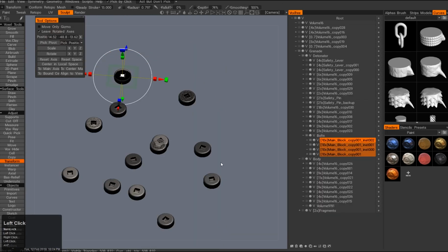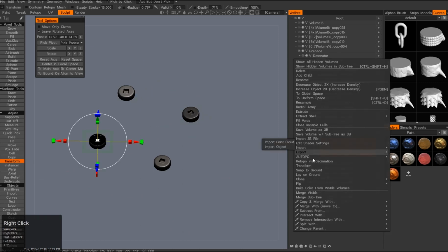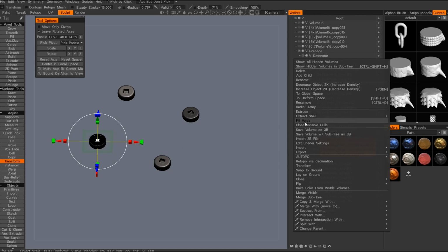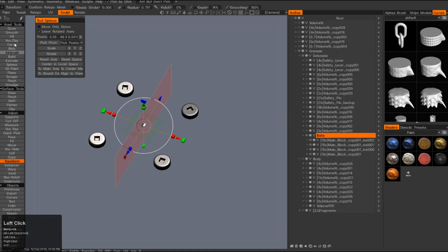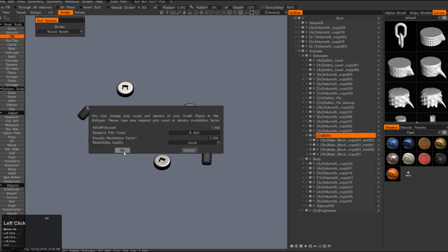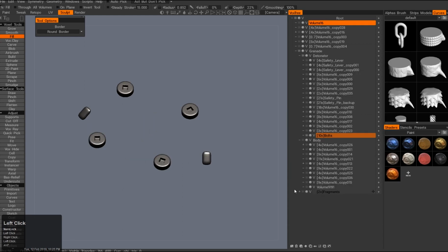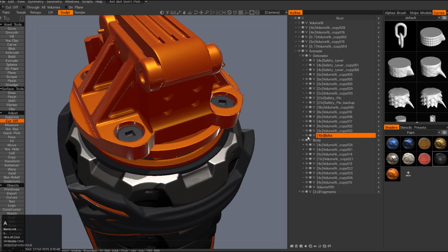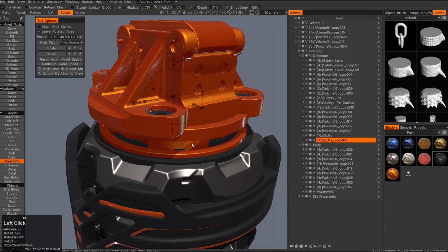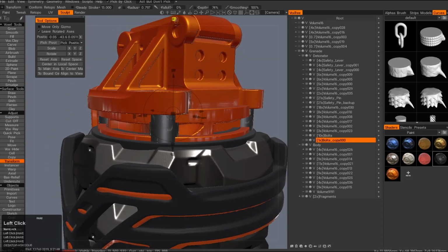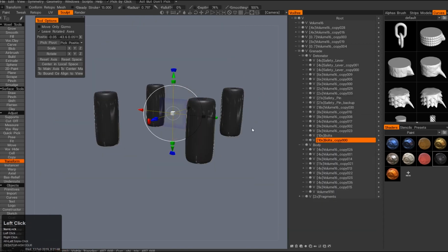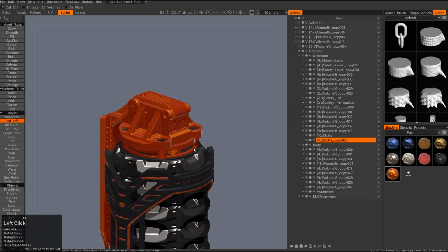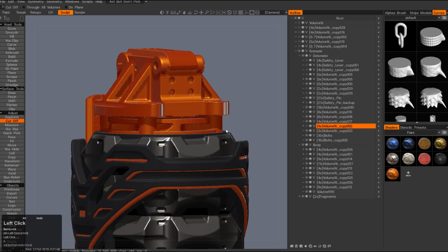Okay, here I was fighting with an issue. I was trying to combine 4 instances together, but if I combine them, then each instance gets extra 3 bolts. And the problem is that an instance in operation is not something that's easy to find. You have to go to the instance tool on the left and use it to uninstance stuff. You can't go into any kind of menu like geometry or symmetry or windows at the top, or right click on the layer and uninstance it. You have to know where to find it, and I didn't know at the time.